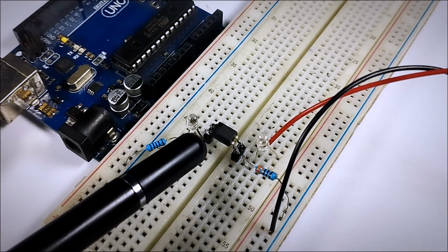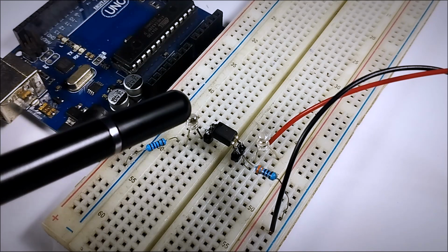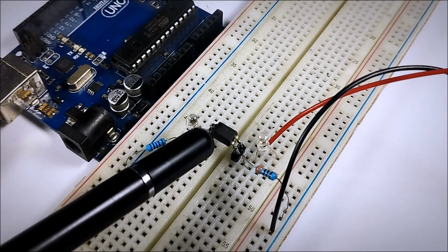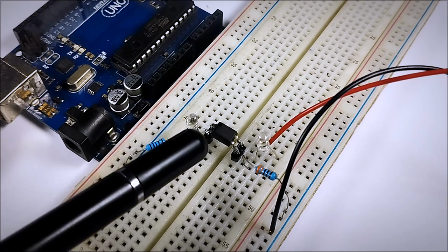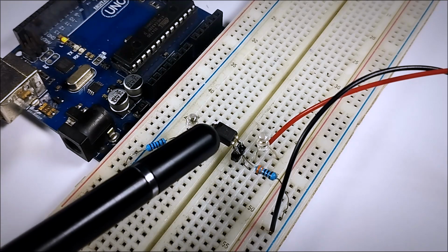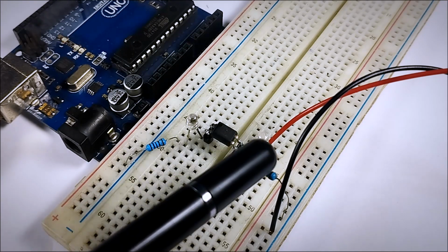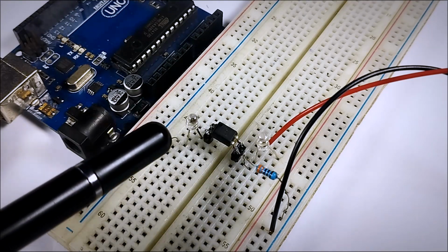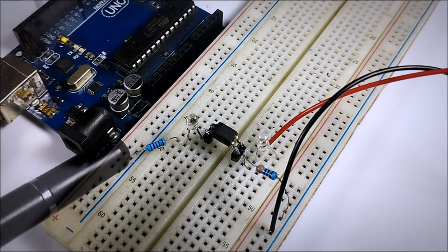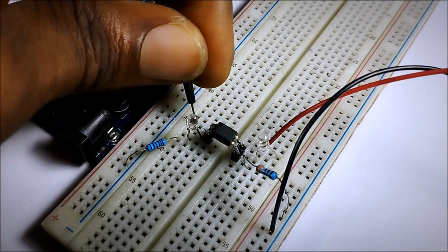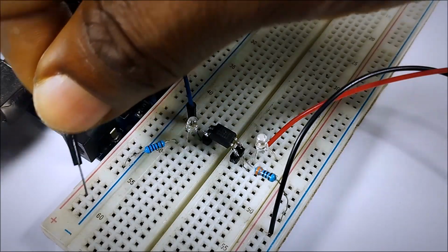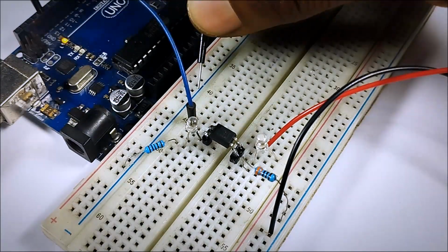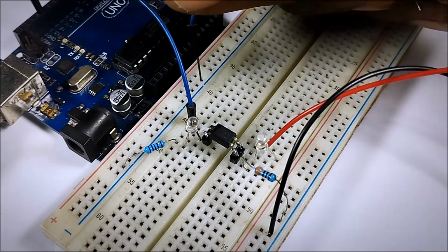Because we can't see the LED inside blink, I just dropped this other LED here, so we'll use it to see the blinking of the LED inside the optocoupler. Whatever response this one gives us is the response the one inside the optocoupler will be giving, and so we can see the reaction on this part of the circuit. We have it connected to a 1K resistor. So we connect pin 13 to our input. Our resistor is connected to the negative rail. This line is all connected together, so we connect that line to our ground.